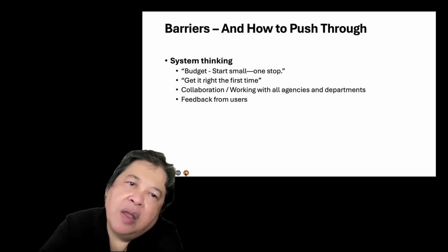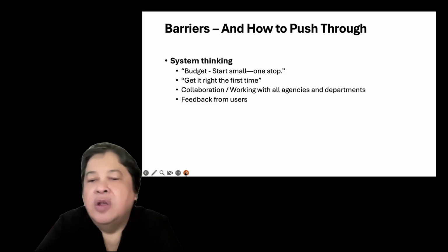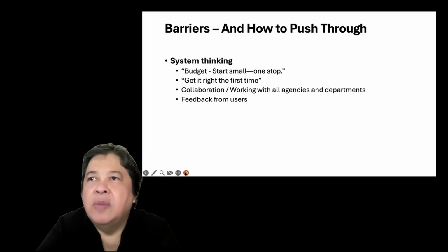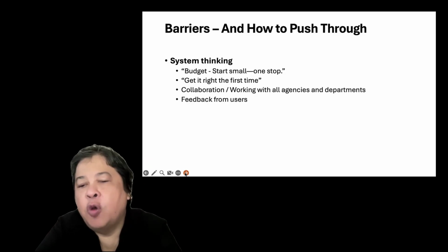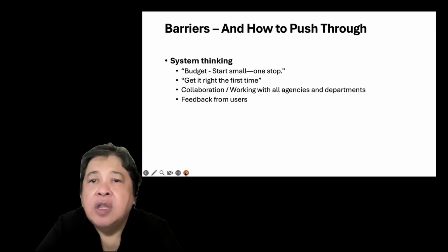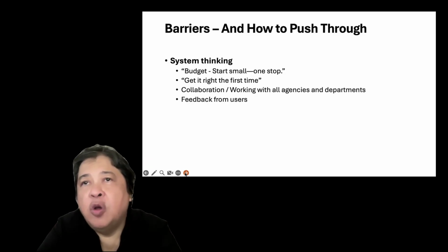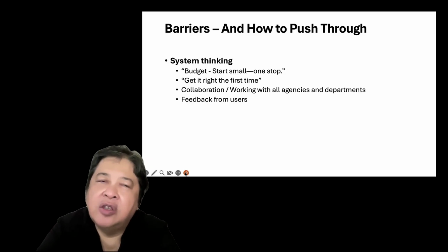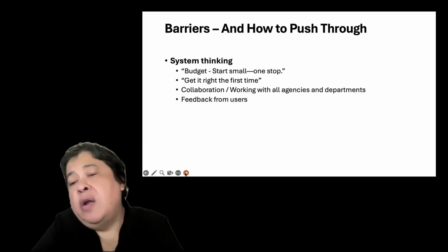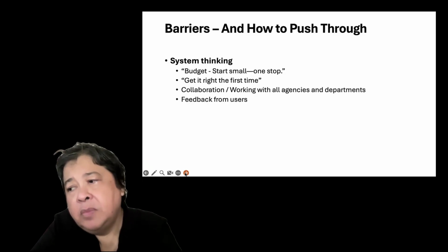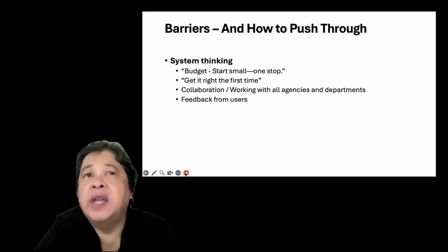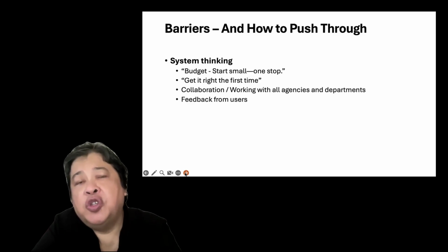So a bit on access audits. After Jim Harrison, an access audit could either use a checklist based on the standards for direct observation technique, or you can interview disabled persons or users, or you yourself could do a walkthrough of the area and determine how accessible it is. So an access audit could be a combination of all three or either or. And it could also come into designing. If you're a designer, you can, from the access audit, design a solution.